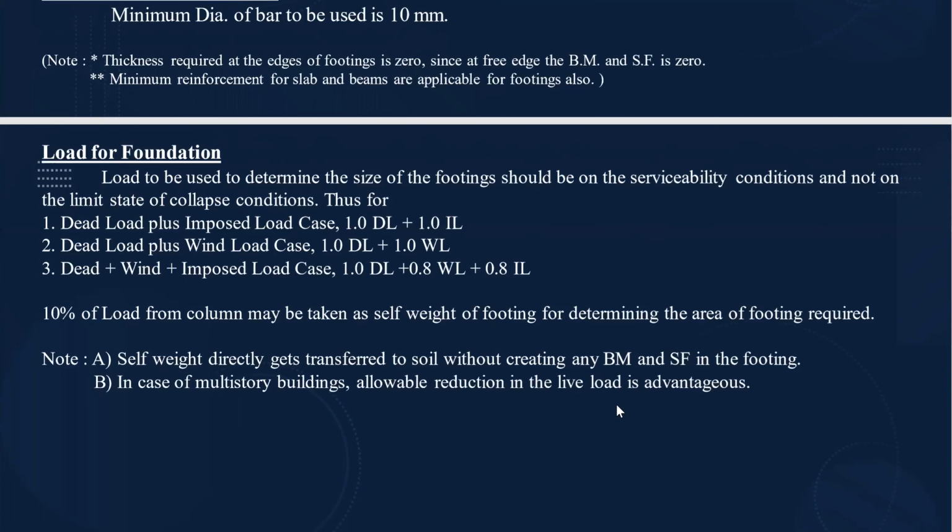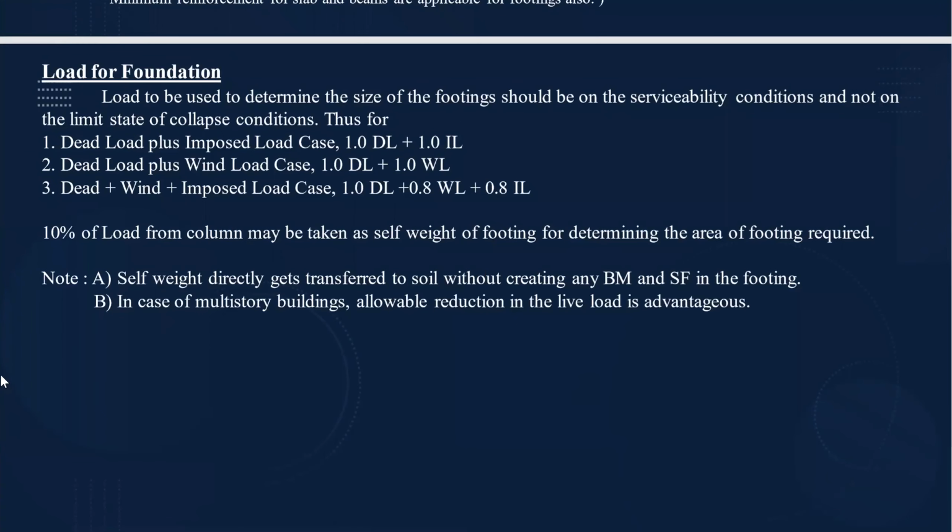Again, there are two important notes. The self-weight directly gets transferred to the soil without creating any bending moment or shear force on the footing. And in case of multi-story buildings, allowable reduction in the live load is advantageous.